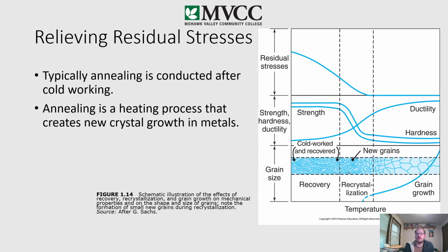Now, that's a pretty big problem, especially for machinists, right? So say they get a piece of cold worked metal and they do need to machine it. Well, how do you actually machine that without, say, it warping, or without breaking too many bits because it's been heat treated to be a high strength, right? We haven't talked about heat treating yet, but basically you can increase that strength, that puncture resistance. So this makes it harder to machine.